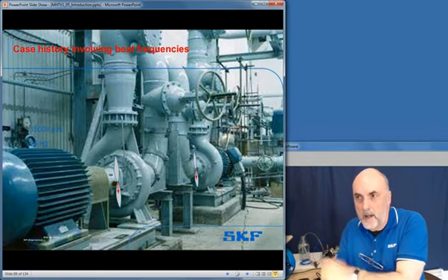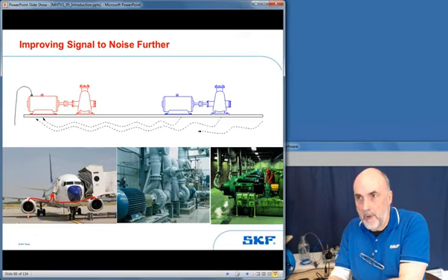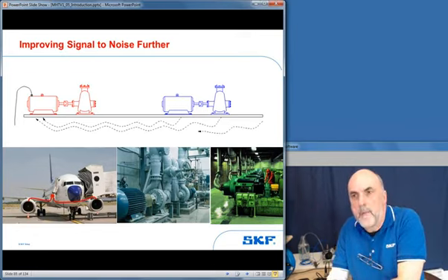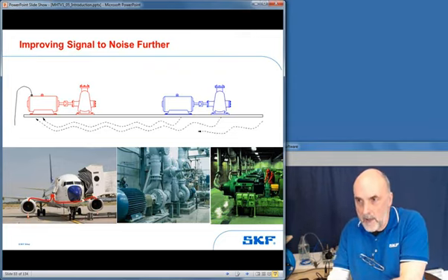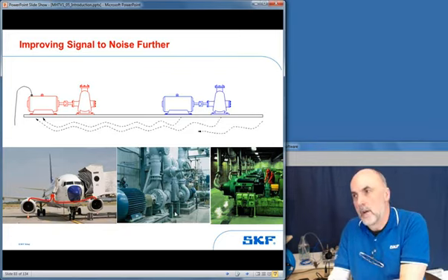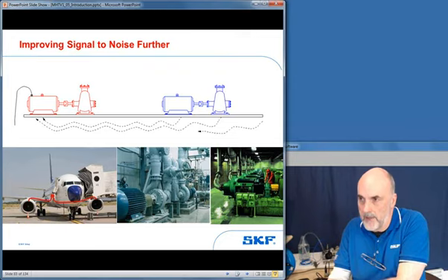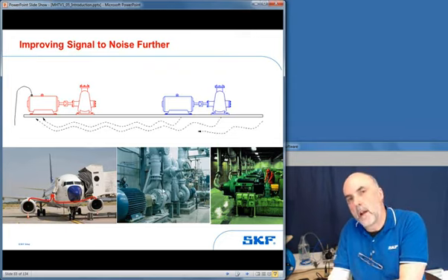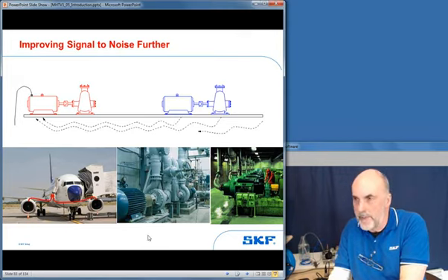So as I mentioned earlier about beats, it does happen. It can happen on aircraft engines. As I said, listen to the aircraft engines as you fly home, or fly to your holidays. Now, it would be nice to ask the pilot to switch off one engine while you measure the other, which isn't very realistic. Or it would be nice to say to your customer, switch off that pump while I measure this pump. In situations where you can't do that, this is where synchronous time averaging comes in very useful.